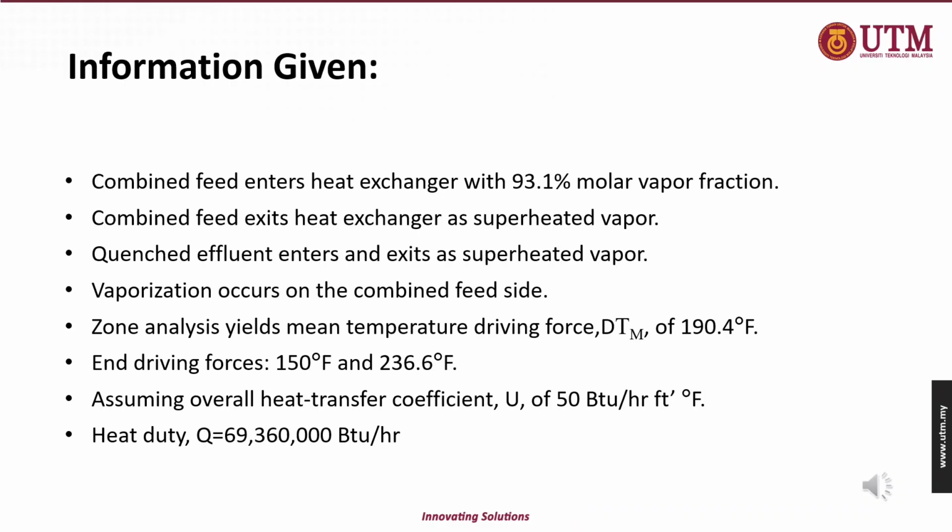The information given: combined feed enters the heat exchanger with 93.1% molar vapor fraction, and exits as superheated vapor. Quench effluent enters and exits as superheated vapor. Vaporization occurs on the combined feed side.